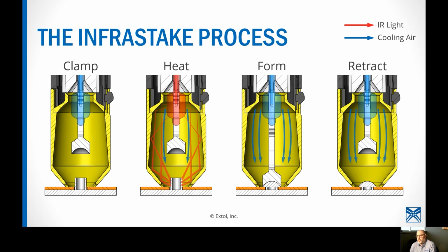It really is dependent upon the part. We have some applications where the bosses are really, really small, less than a millimeter, and we can do cycle times in 2 or 3 seconds. All the way up to bosses that are very large, think 10 millimeters. I mean, something that would retain maybe a door panel together or a pillar inside of a vehicle. Those could take up to 20, 25 seconds. It's really dependent upon the geometrics of the part and the material that it's made of.